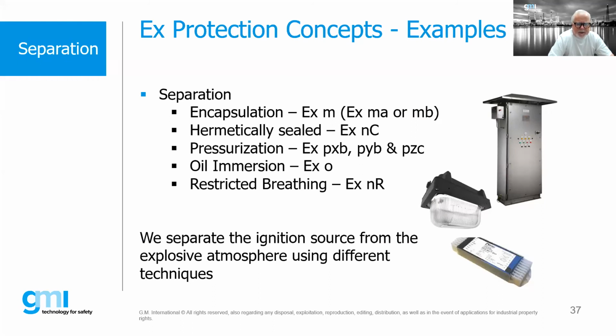As an example, intrinsic safety, every now and then somebody will ask, hey, can I make a motor starter intrinsically safe? Or can I make a light fitting intrinsically safe? Well, generally no, because you require more energy to operate than what is allowed under the use of intrinsic safety. On the other hand, it makes sense for transmitters and thermocouples and RTDs and solenoids. For those, the protection concept of intrinsic safety makes great sense to use.